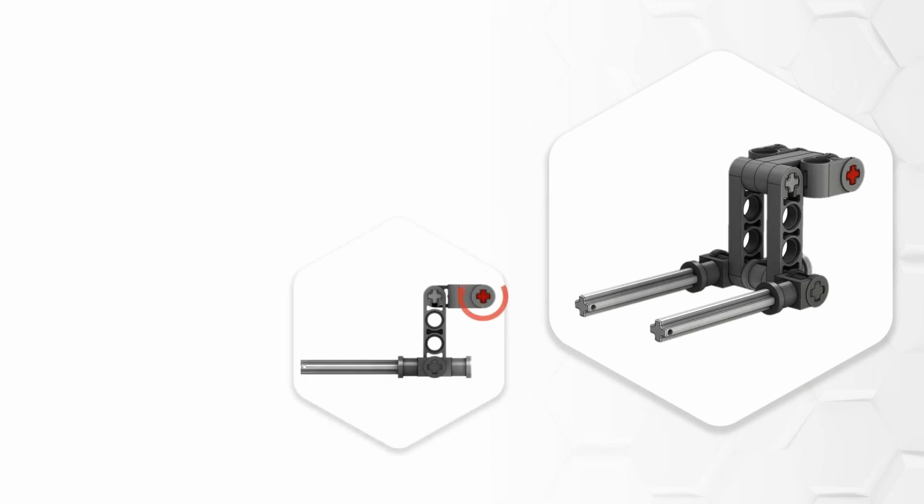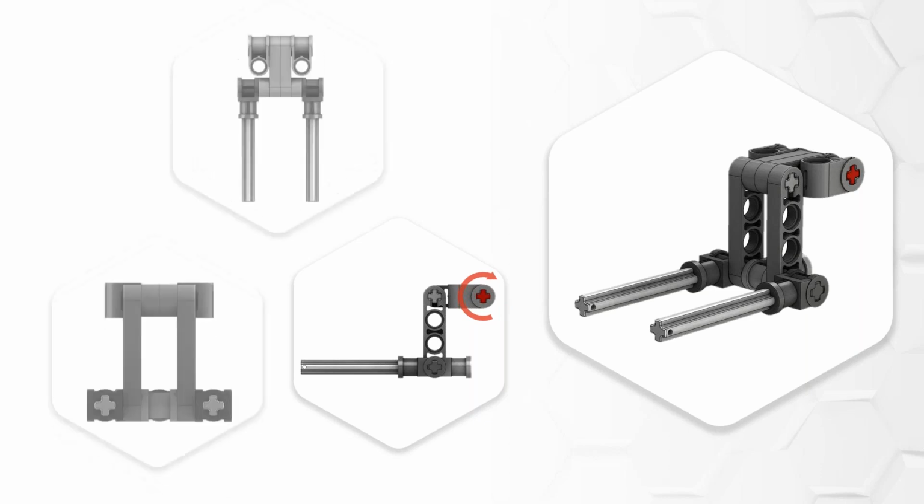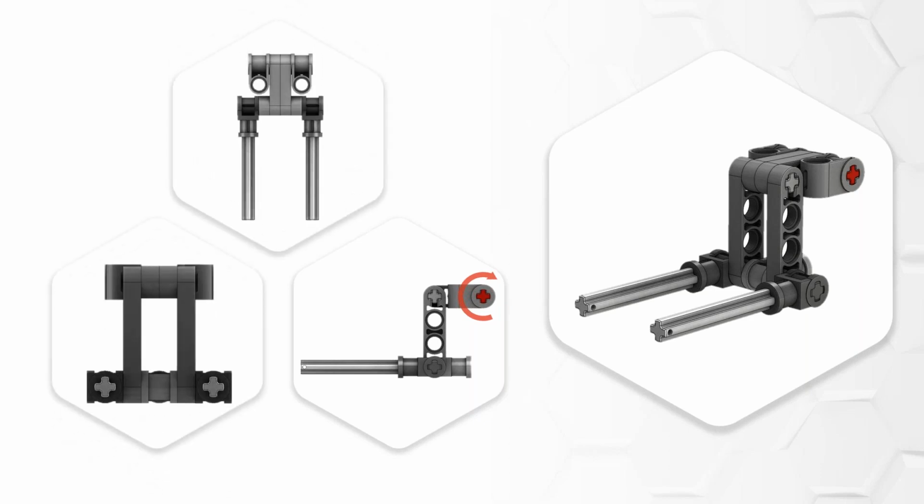important. The reason that I pick that red component that you see there is because this assembly will actually pivot on that axis. So it sort of makes sense to make that the first component and actually fix it. The other thing to look at on this assembly is that if we look at the top and bottom views of that assembly, you can see that it's symmetric. So we can also use tools like symmetry just to make our lives a bit easier for that.